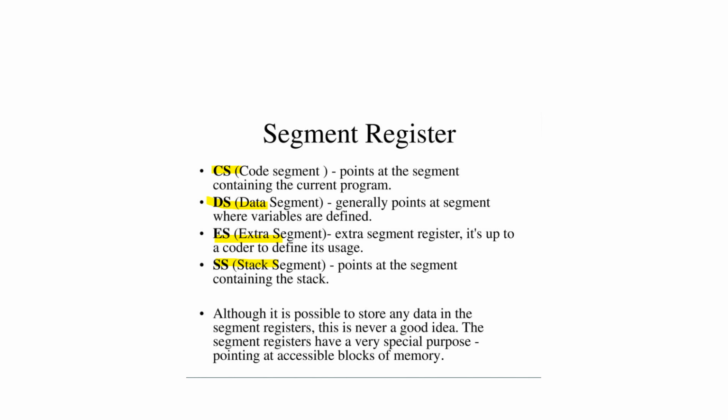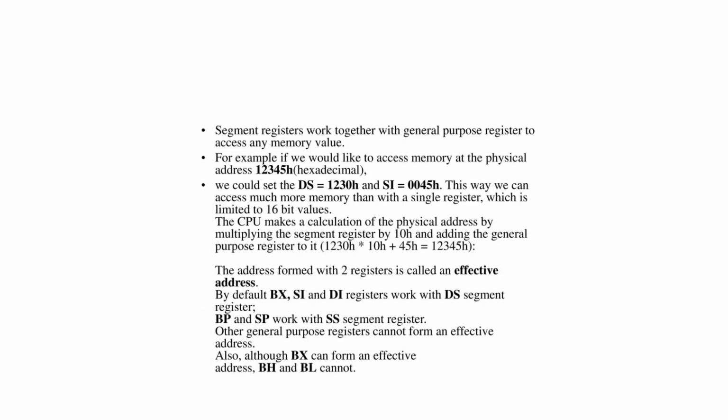So the programmer won't get confused, and the programs can be executed successfully without any error, which these kinds of errors will happen in 8085. But due to the splitting of the memory location like code segment and data segment, the programmer won't get confused, and the program can be successfully executed.